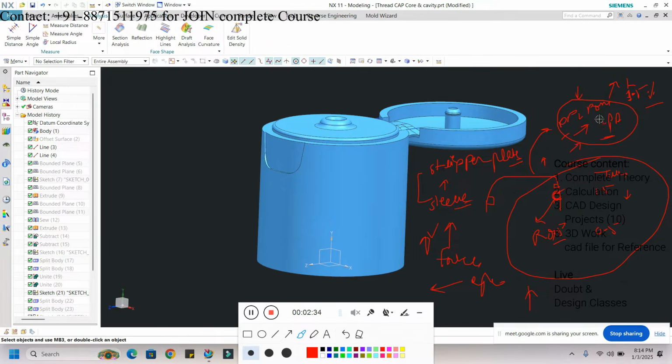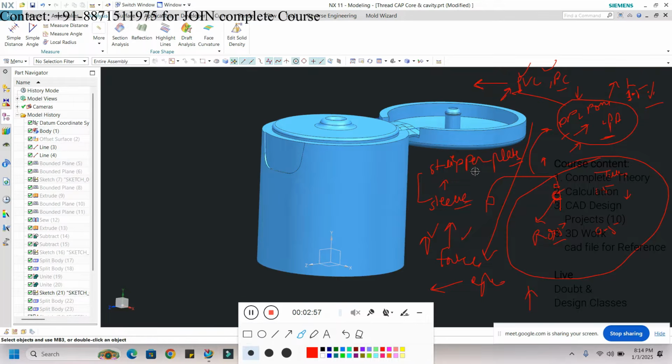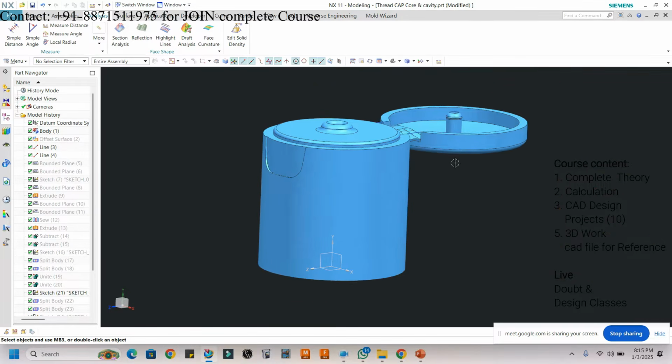But if we have a material like PVC or PC, we cannot go with this jumping out method. Why? Because it's a quite rigid material. So basically, if we deal with PVC and PC with this force ejection, it means the undercut or the component can be deformed.